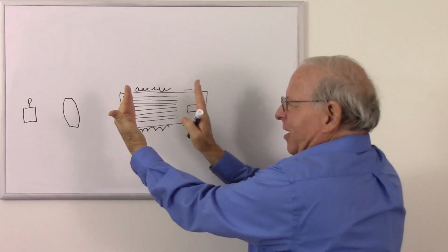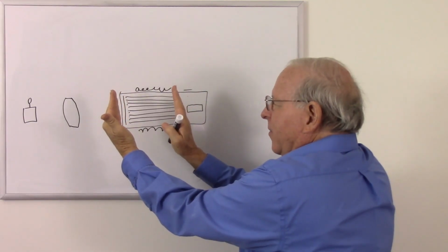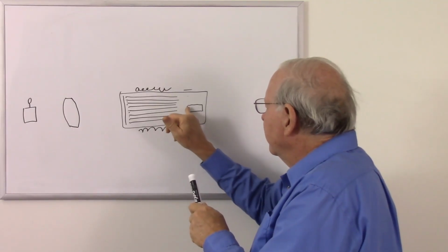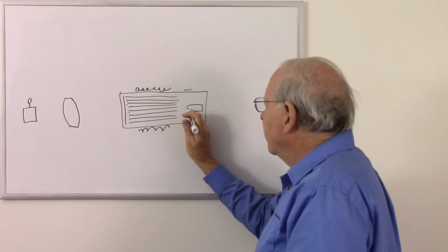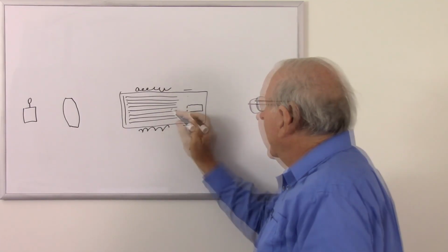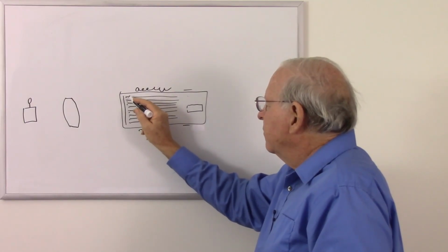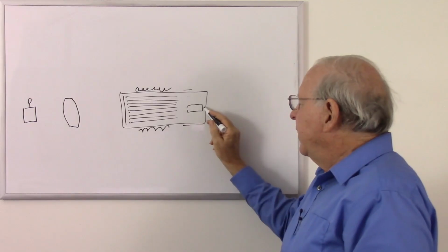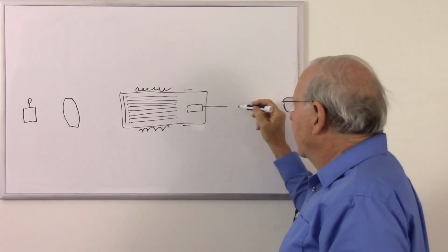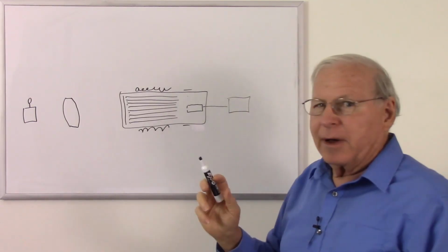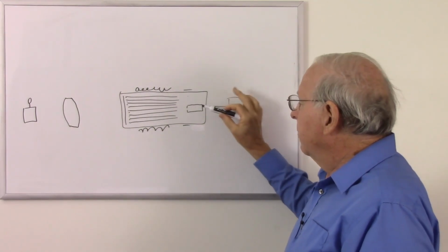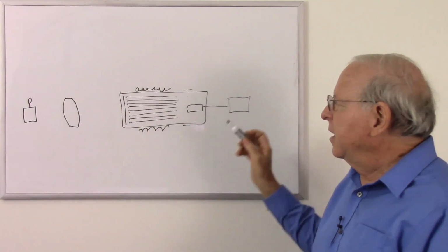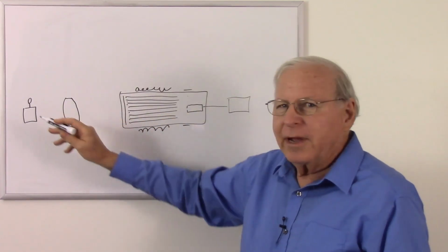So if you can picture an image of our candle here, we're steering the whole image around so that only part of it enters. Put a little aperture here for our phototube, and only the electrons from a tiny part of the screen here would actually enter this phototube, and that would be taken out and processed through a lot of stuff I'll talk about in a moment to create something that could be reassembled in the cathode ray tube to be an image of what we have here.